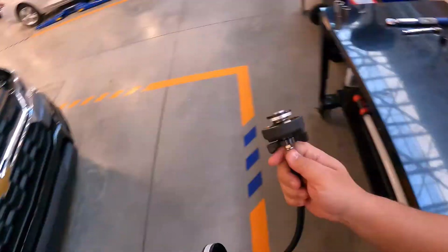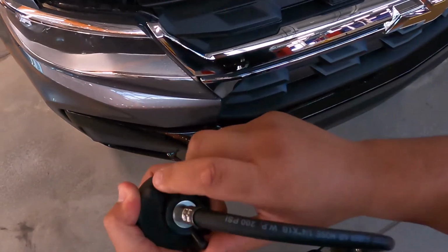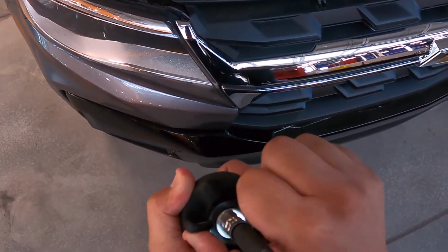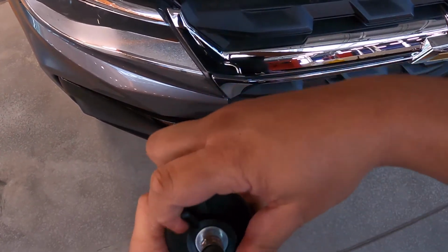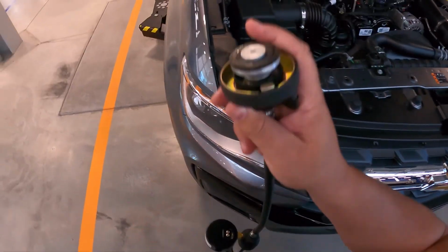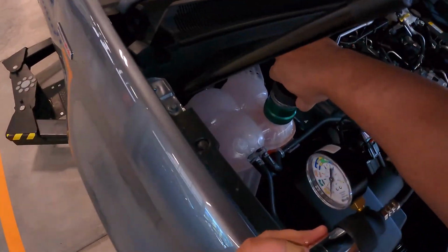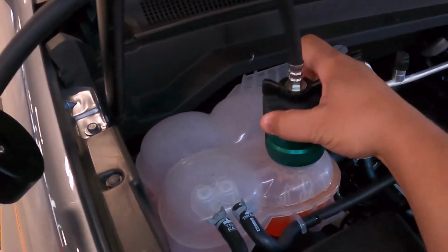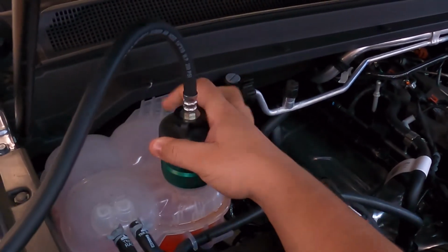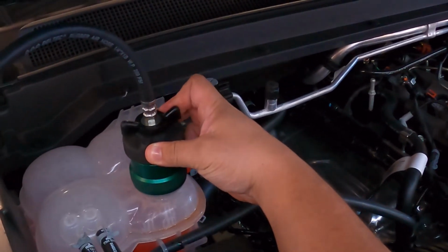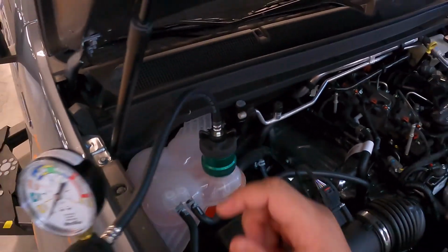Then go ahead and grab your pressure tester. I'm going to slow it down and zoom in here. When you install the pressure tester, you're going to make sure the wing nut is in line with those ridges. So you're going to turn the wing nut so it pops up on those ridges. Now it's ready to be installed. From here, you're just going to take it to the adapter. I'm going to zoom in again. You're just going to rotate it, keep rotating until it stops. Like righty-tighty, it should stop. Once it stops, then you're going to turn the wing nut, turn that perpendicular, and bam, now it's sealed.